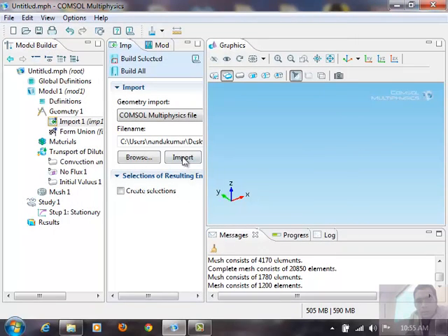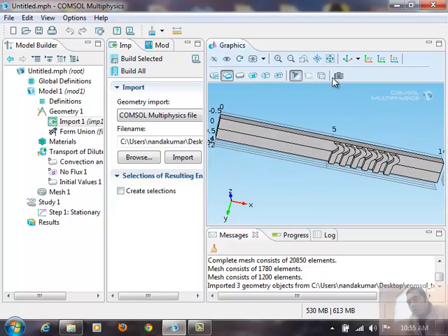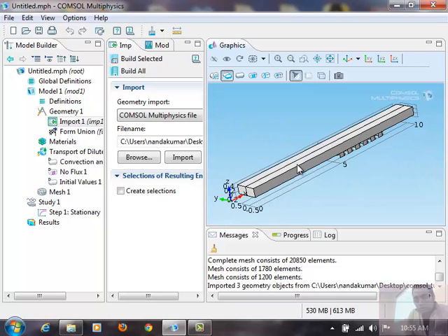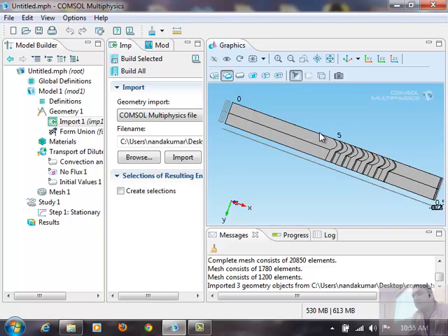So it's a rectangular main channel, and then we have grooves here, which are extruded in the negative Z direction. So construction of this geometry is not tough. You can build these rectangular blocks, and then, again using the same work plane, you can construct one of these curves using Bezier curves. Once you know the parameters, you can use array features to construct from one curve the rest of the 6 curves, or whatever number of curves you want. And once you have selected all these curves, you can extrude them in the negative Z direction. That's how we have generated this geometry.